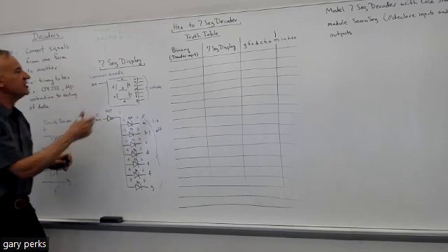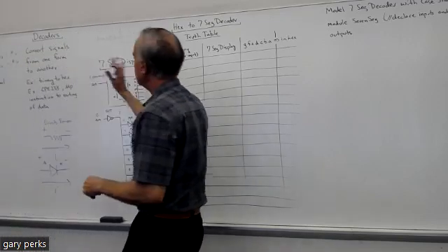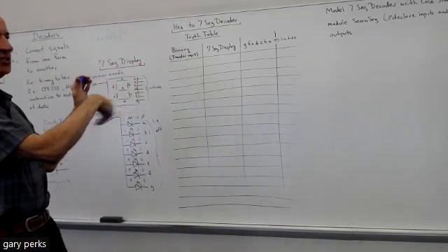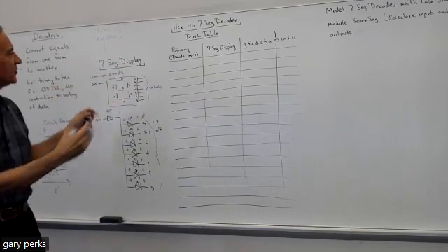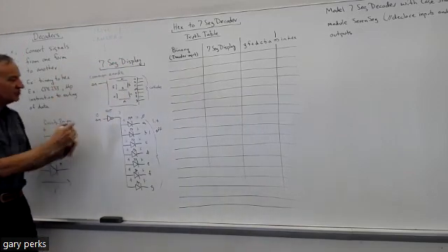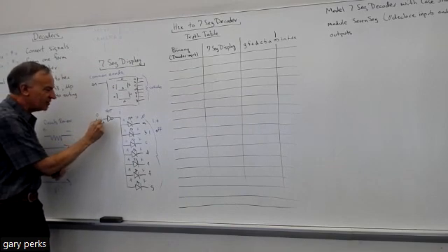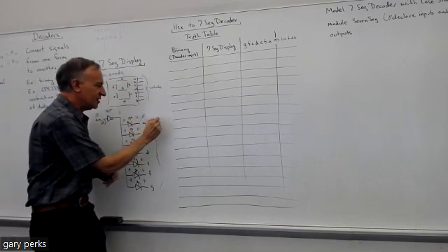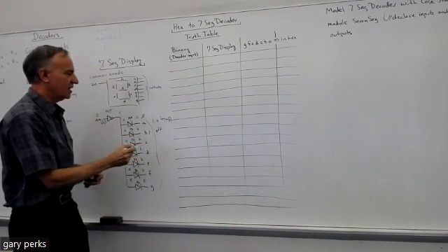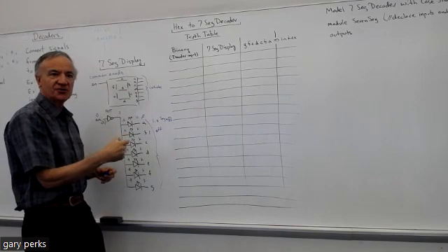Say this is the furthest to the right, when you're looking at your Basis board with the switches on the bottom. The furthest right 7-segment display is the 0th display. So this would be AN0, and seg A0, seg B0, and so on.